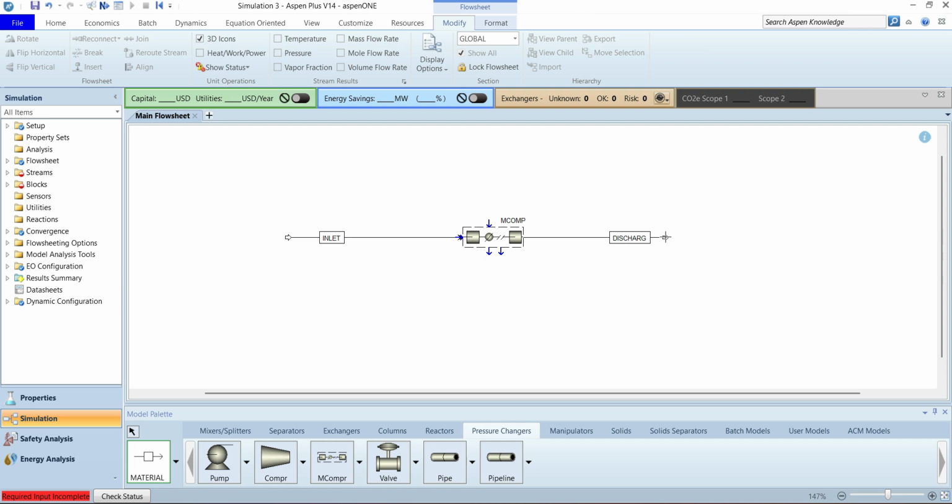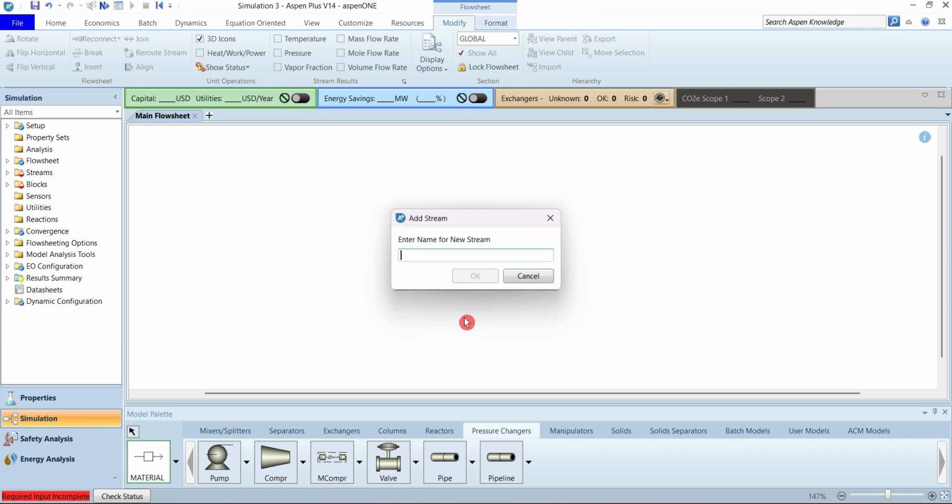Since we are intercooling and there is a humidity in the air, so probably there will be a condensate formed, and for the condensate we need to define an appropriate condensate discharge stream. So for that purpose you can use this liquid knockout. So use 3 liquid knockout streams.